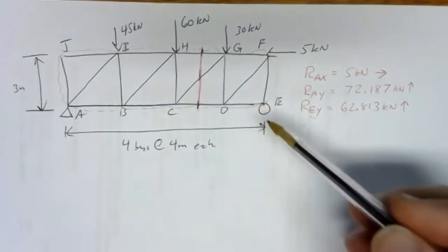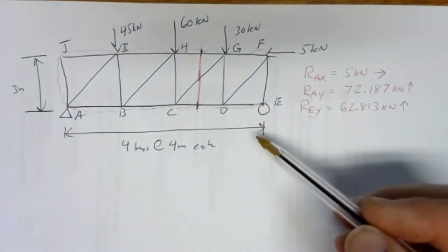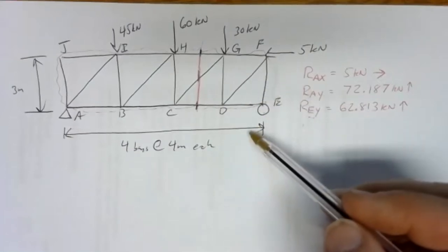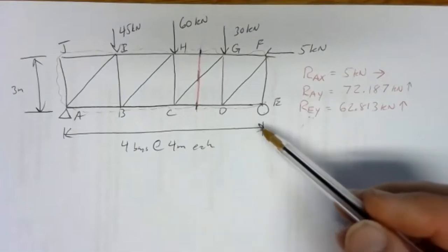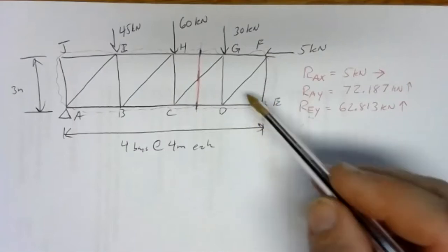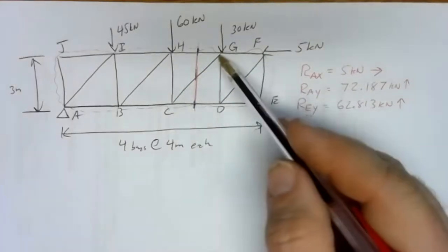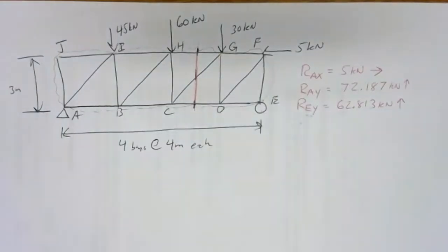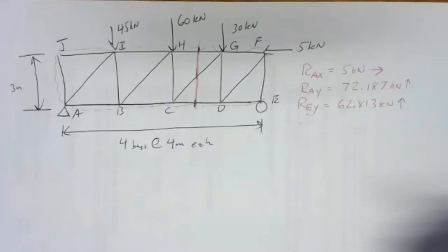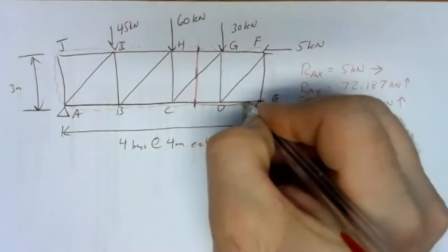So I think in this example, even though it's counter to what I've drawn in the notes, and as you practice on this, you could go and work it out as it's drawn in the notes and see if you get the same answer. You should. The answer cannot depend on the method we use to set up the equations. Equilibrium is equilibrium. There's one force in this member. It doesn't matter how you find it. Can't depend on what method you pick. You're not going to get a different answer for method of joints, method of sections, closing to the left, closing to the right. So I'm going to close to the right on this one as an example of how to do that. So that'll be my system boundary here.